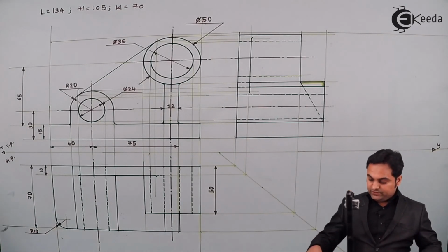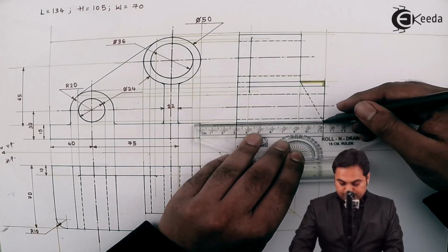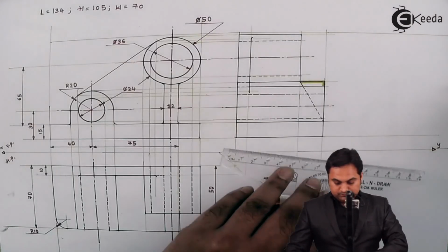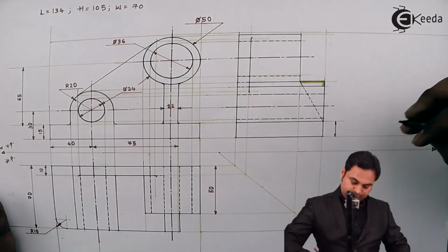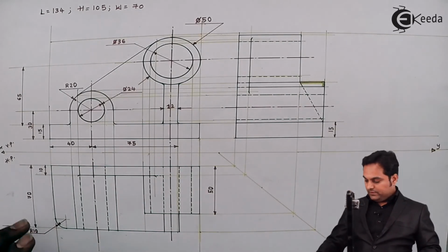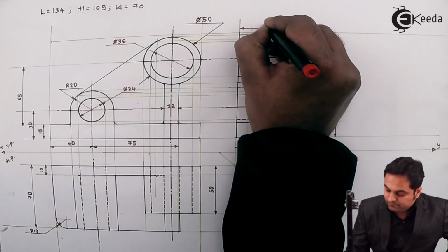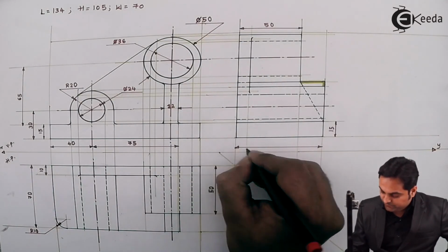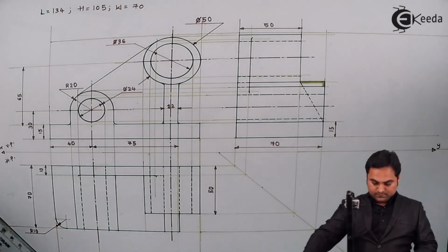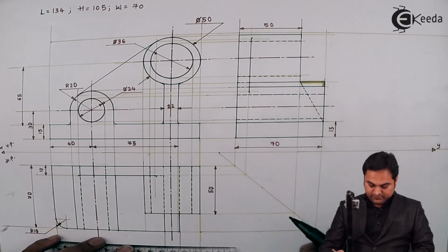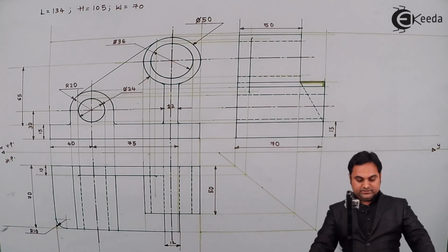Next, we can give the dimensions in the side view as well. All the major dimensions, mostly we have given in the front view. Again, this block of 15 mm height. Next, the center distance we have already marked. 15 mm, and then marking the width, 50 mm at the top and 70 mm at the bottom for the cylinder and semicircular part. So this is the last part which is left, with length of 12, and with this we complete the problem.